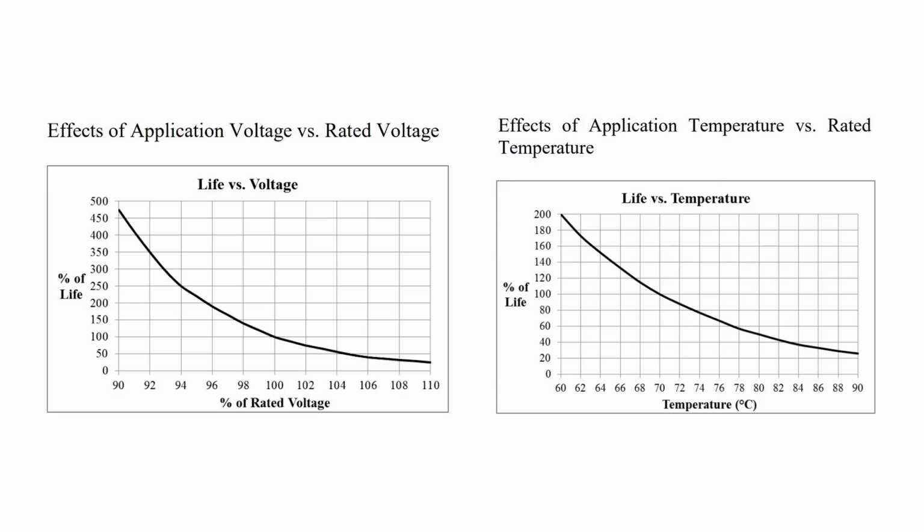It's somewhere between 10 and 20 years, depending on what part of the country you're in. It's a long time of running a typical air conditioner. And they're tested so that they should work fine up to 70 degrees Celsius for 60,000 hours, not 70 degrees Fahrenheit, so that's 158 degrees Fahrenheit. Case in point, under normal operating conditions, capacitors should last a really long time if they're keeping their manufacturer rating, and if they're tested properly and made properly. There are several different standards, but the old U.S. Tecumseh standard is the 60,000 hours at 70 degrees Celsius.